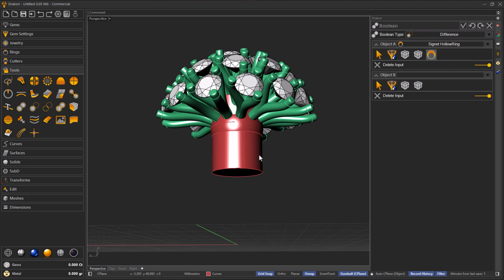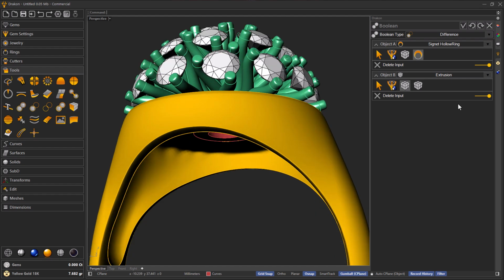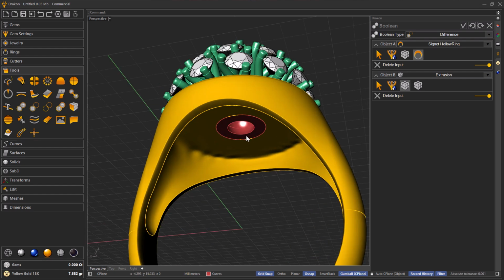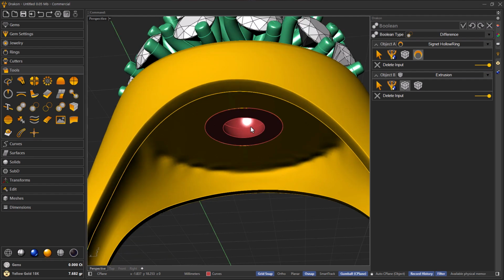But in this second object, since it is a Rhino object, if you delete input, you lose the possibility to edit further, which means that the Rhino object will disappear from the document. So you can't edit if you want to change it in further steps.